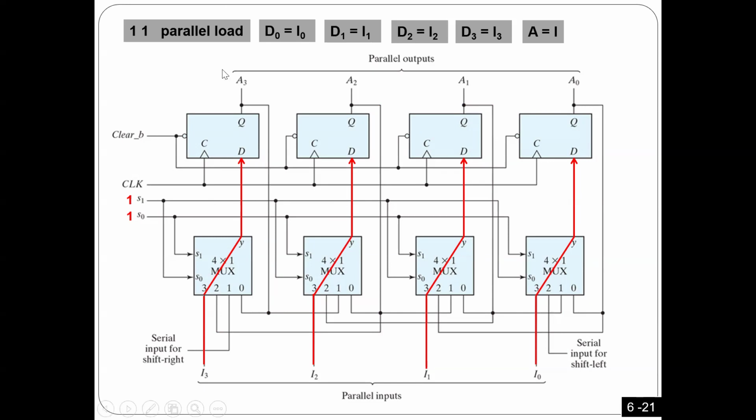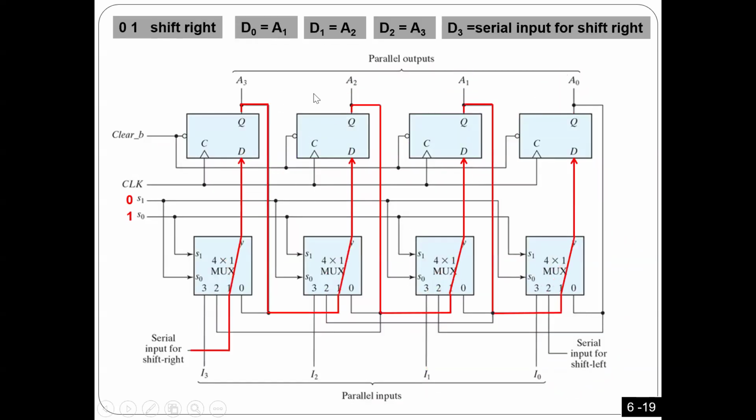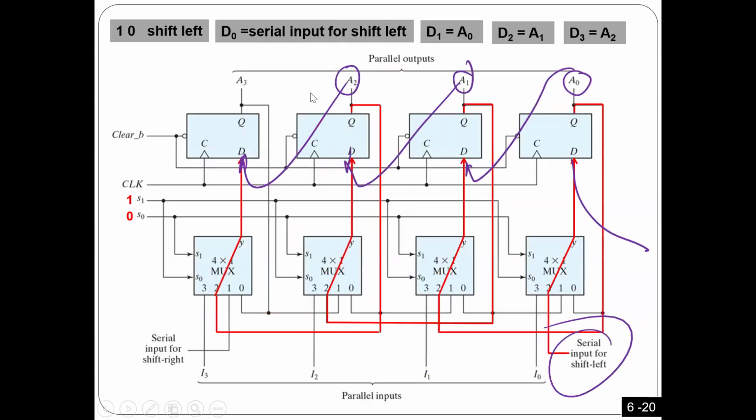Anyway, this is not going to be in the exam. Again, this part is difficult. Registers: now I explain what a register is and how you can make it using flip-flops. I explain shift right and shift left registers. It's very easy. You see how I connected the circuit: the output of one flip-flop is the input to the other one. Rotate is just a special case of shift.